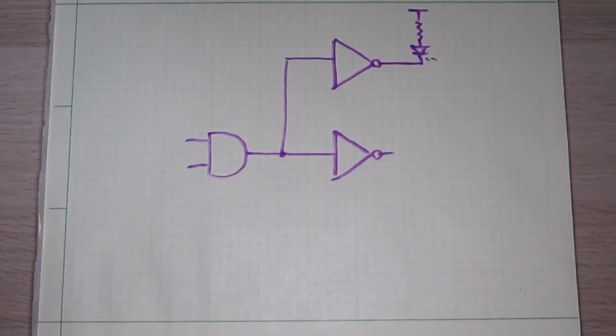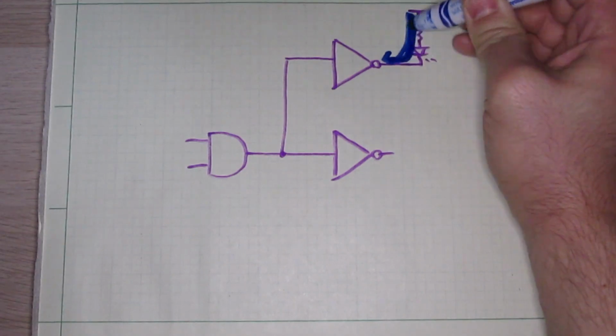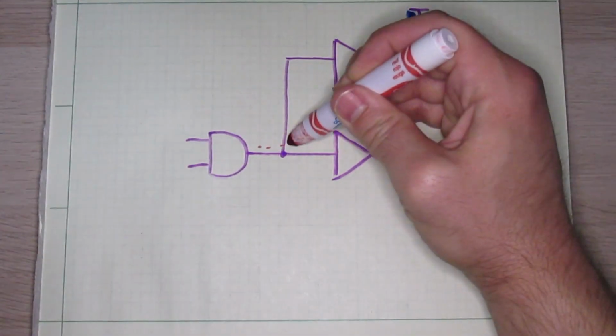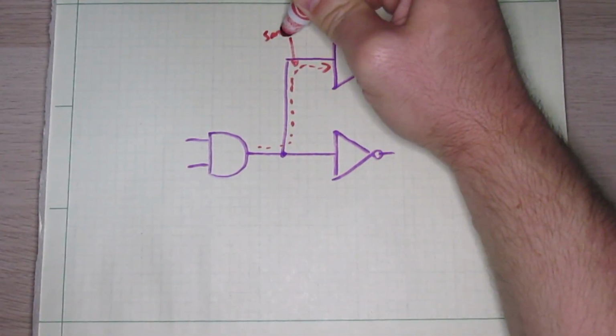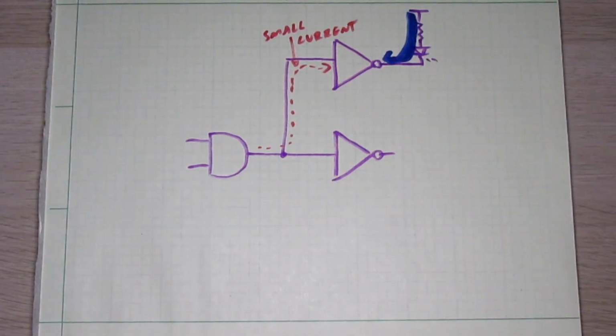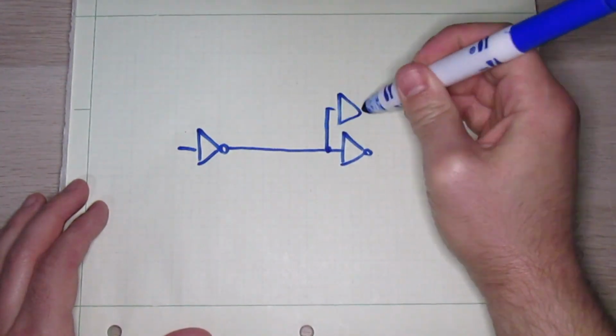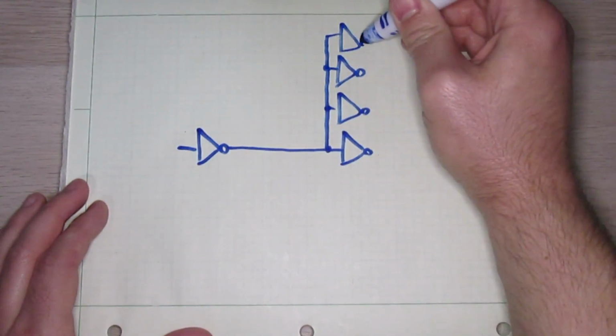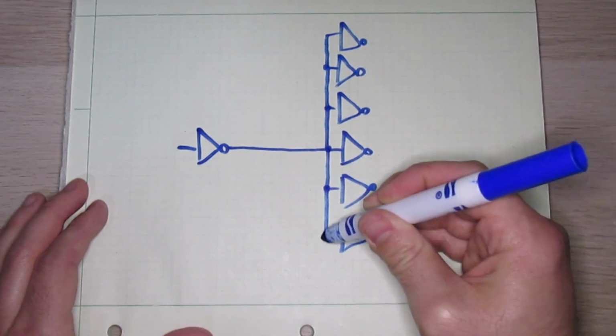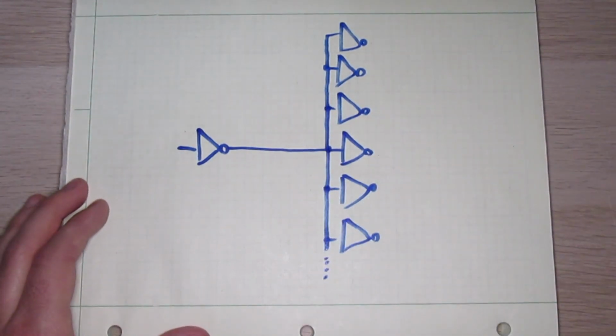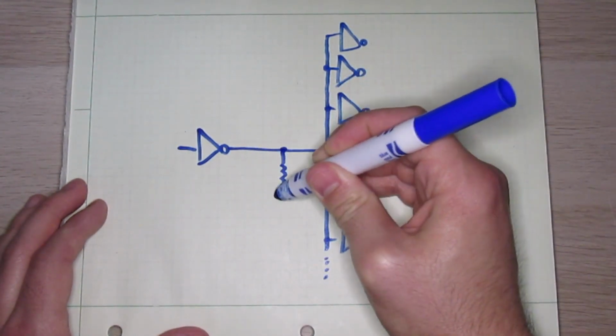When we do this, it'll still affect the circuit that we're trying to measure a little bit because the input of the buffer still draws some current, but it'll be much less than the LED would draw on its own, and so it usually won't break anything. So tell you what, let's do this. Let's build a circuit that has as many inputs as possible attached to a single output of a gate. And that will represent whatever circuit I'm trying to test or debug. And then we'll just put some LEDs on it and see what happens.